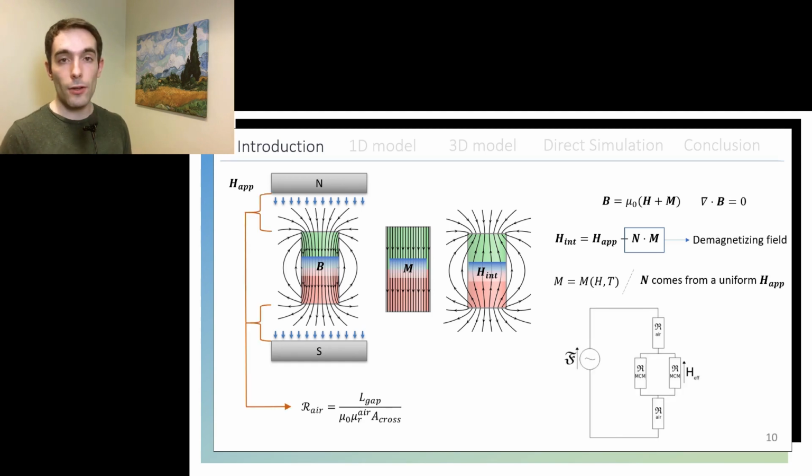And that is another aspect of modeling the magnetic field, that the applied field is never uniform. That can be approximated as well by resolving a simplified magnetic circuit between the poles of the magnet. So we would calculate the reluctances of the materials that are between the poles, and then we would solve a magnetic circuit that is an analogous concept to the electrical circuit, so the effective magnetic field on the sample would be analogous to a voltage.